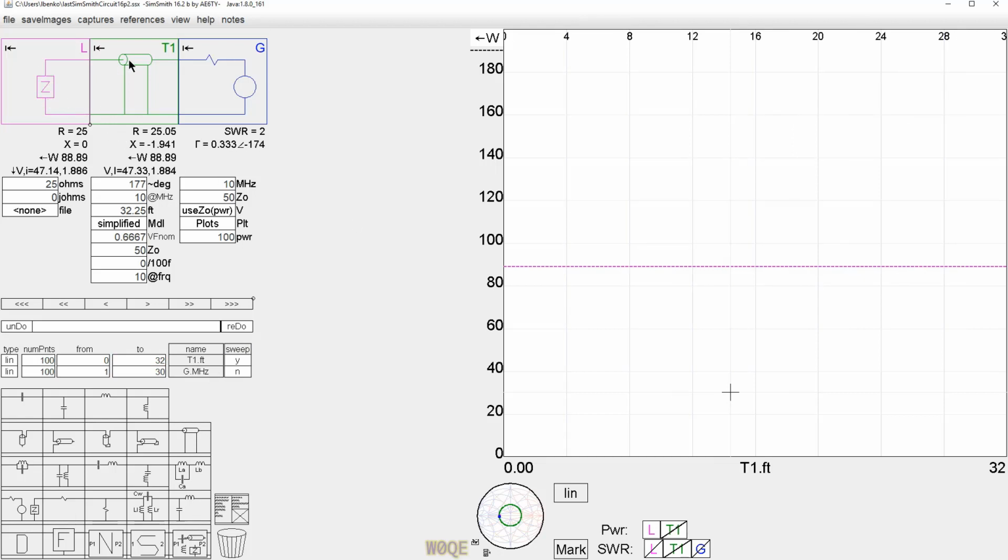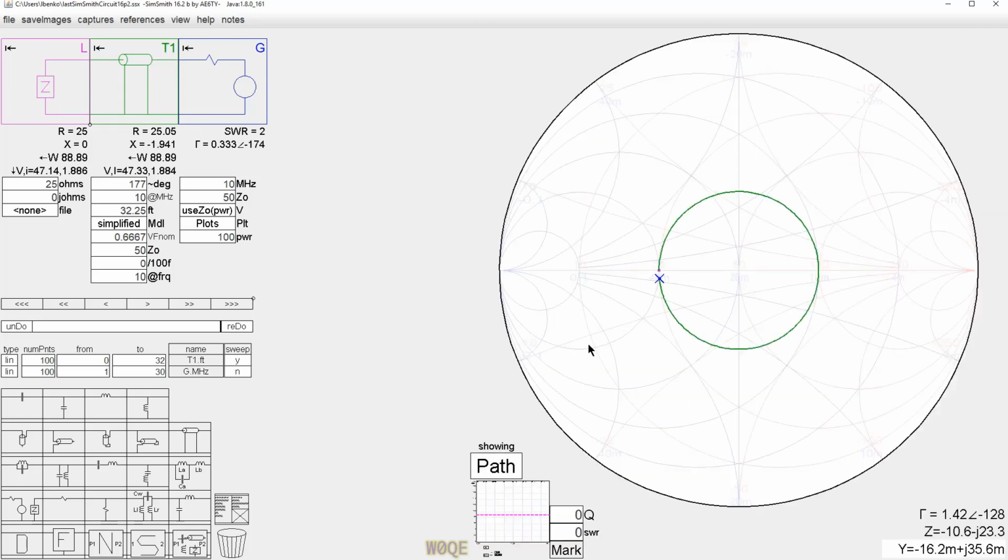And that means that the impedance we see right here, if we look at this impedance, it's all of these impedances right here. So that generator was centered at 50 ohms. A lot of solid-state transmitters will be centered a little bit less than 50 ohms because of turns ratio issues, and particularly the fact that we only have 13 volts to drive the amplifier stage. That's just the way things are. But anyways, it's close to 50. So this represents a good use in general for almost all cases in SimSmith.